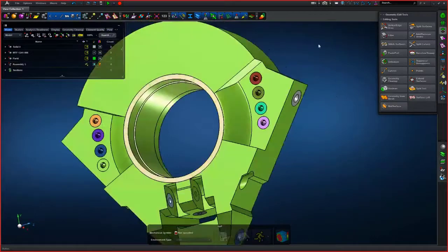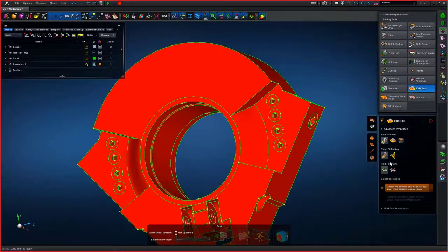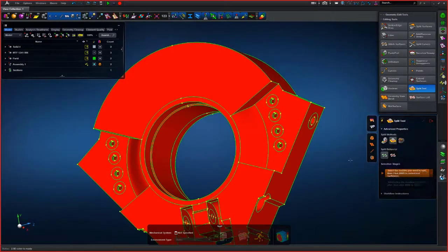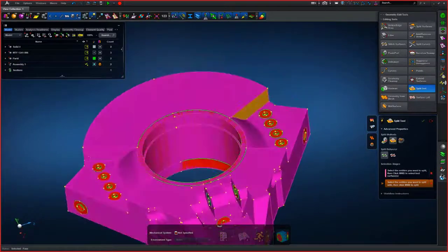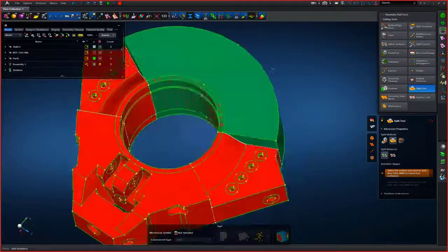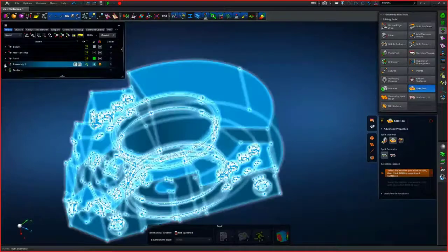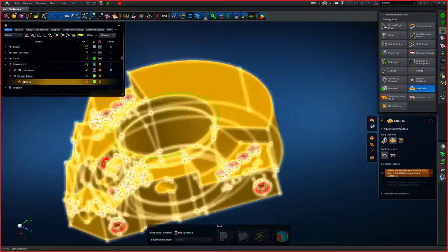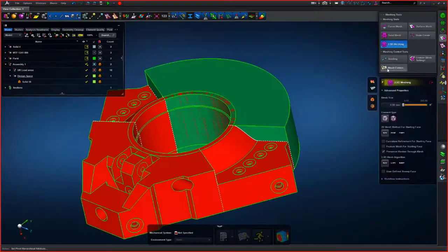Partitioning is also useful when we do want to use a hex meshing in a model. For instance, and I'm not going to do the whole model, but I'm just going to show you this quick example of using the split partitioning option on a large body like this, picking two surfaces as a guide on how the structure should be split. And now we see that a portion of this solid, and it's still only a single solid, can be hex meshed. So let me just show you that that is true.